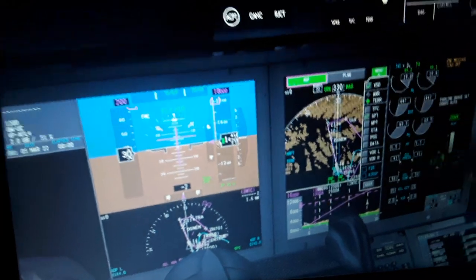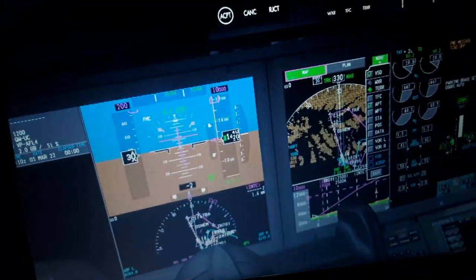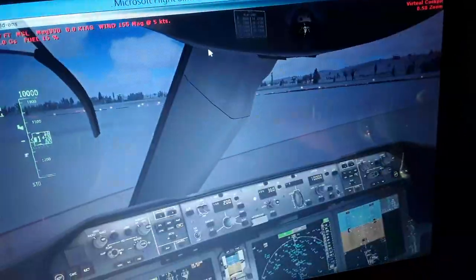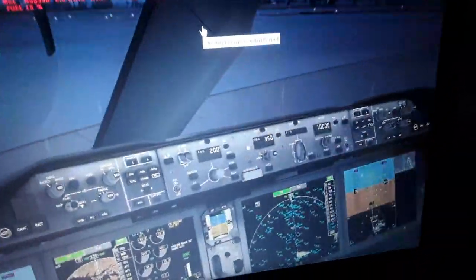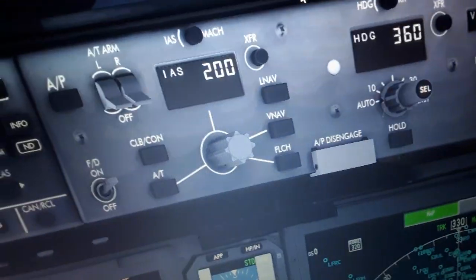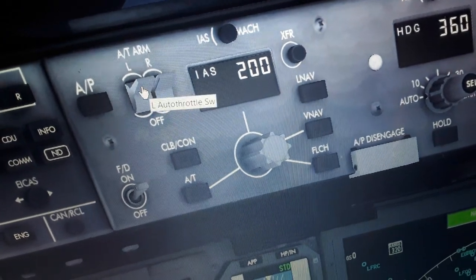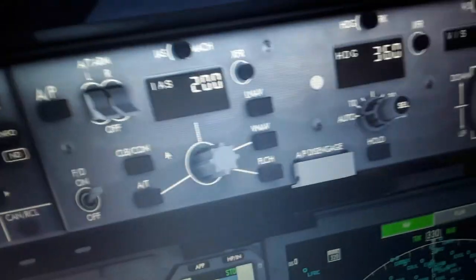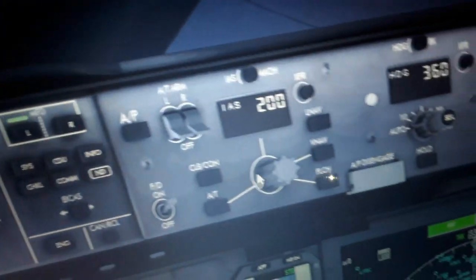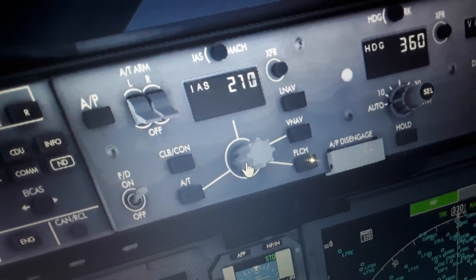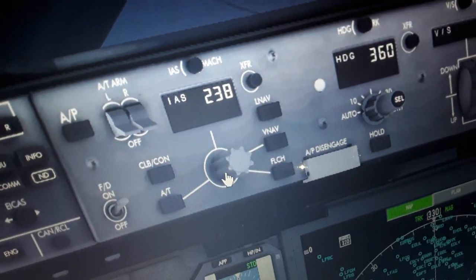So we're gonna set also the autopilot, the airspeed, and the barometric altitude, target altitude, heading. You can see also the display here. The HSI displays a few things, as you can see. So we're gonna set the autopilot flight director system panel here. As you can see, we have the autopilot engage and disengage switch over here. The auto throttle left and right, engage and disengage flight director. Also the airspeed, we can set the airspeed guidance of the aircraft, so we can change to whatever value we need for flying the aircraft.